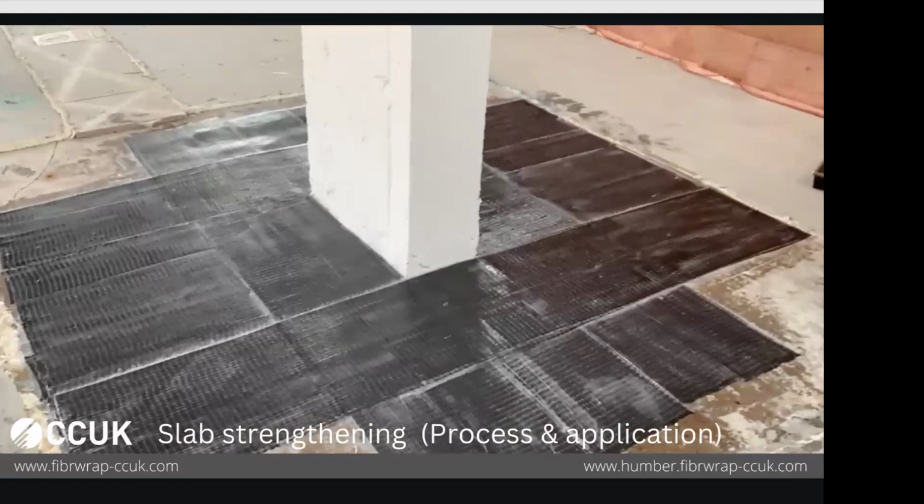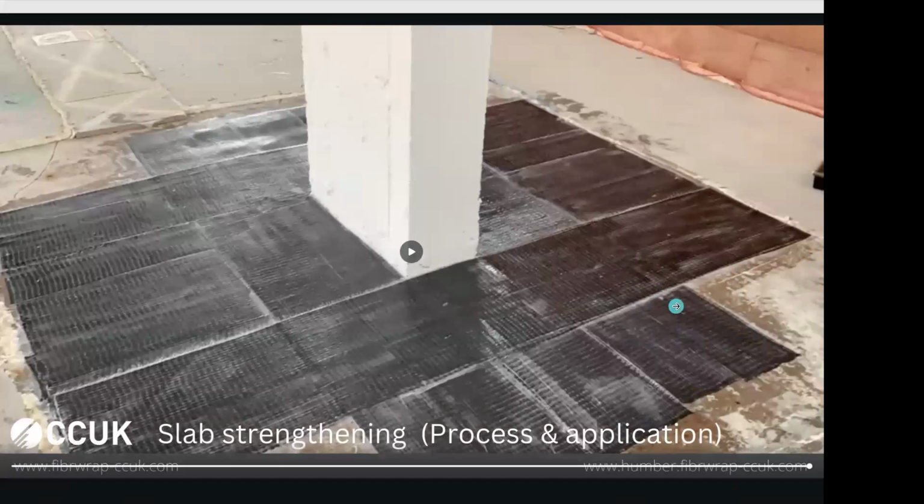There are still people out there who do dry layup. So in dry layup, what you do, you just prime the area using pure epoxy and then try and patch a dry fiber with your hands on it and put another coat of epoxy on that dry fiber. Now that dryness in the fiber would lead to a debonding and delamination failure because you cannot guarantee the 100% resin impregnation. And for that reason, dry layup is more or less abandoned in the UK, and it should not be used in the UK and Europe, and it should not be used anywhere. So if you ever come across, especially the fabric application in your country on one of your projects, make sure the contractor is doing the wet layup method.